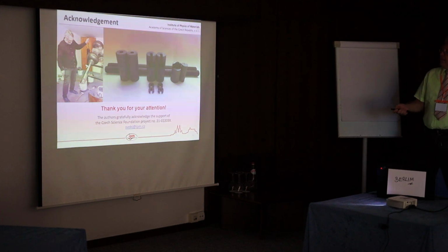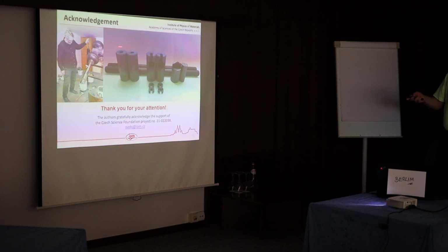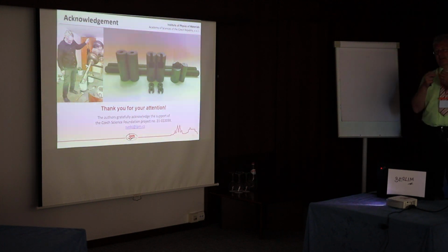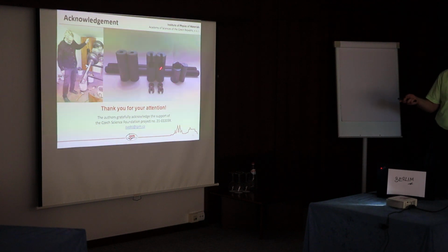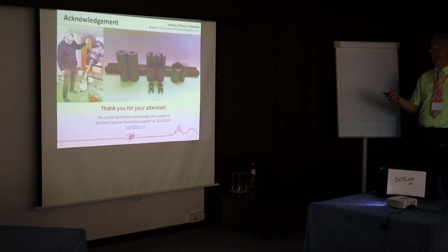In fact, we have creep machines which had problems with grips. That's why we made grips from this material, our material, because the nickel-based superalloys are not able to do tests at 1300 degrees. And we don't have ceramic grips. It's problematic, the ceramic grips. It fractures often, it's very expensive. So we made these grips, and now we will start really the heavy creep series or heavy creep campaign.